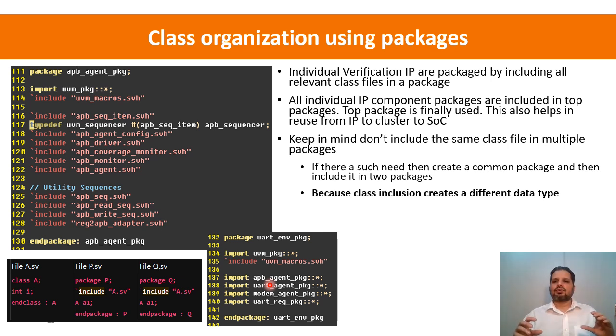That's a horizontal reuse. And there is a second reuse, that is, let's say I have built my UART environment, and then the same UART gets integrated into the SOC, and I want whatever environment that I have built to be available at SOC level. So I can use part of it as is. Not everything gets reused. At SOC level, the way things are done is different compared to unit. We will look at how it is different in future sessions, but still part of it gets reused. So when that happens, I can just import the UART environment package,